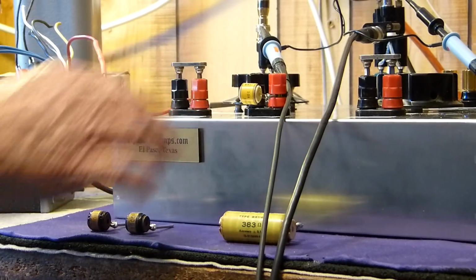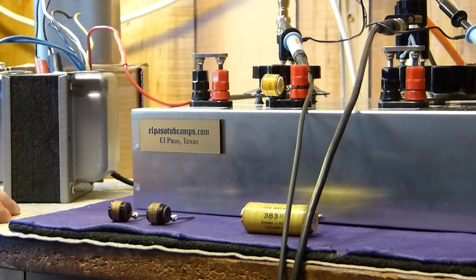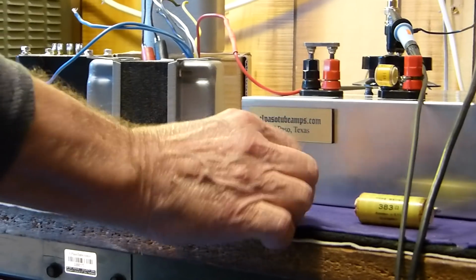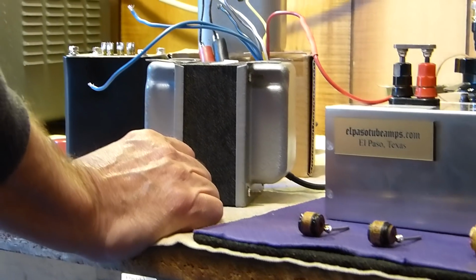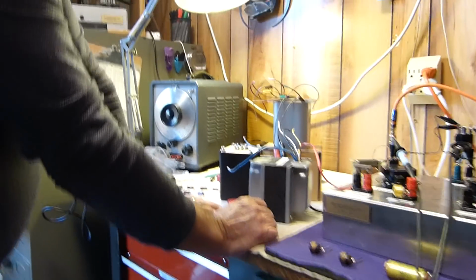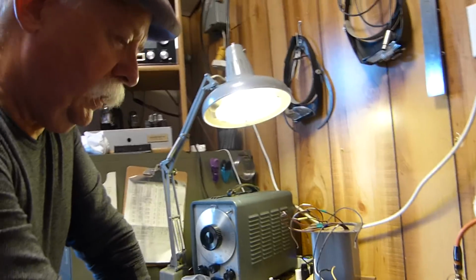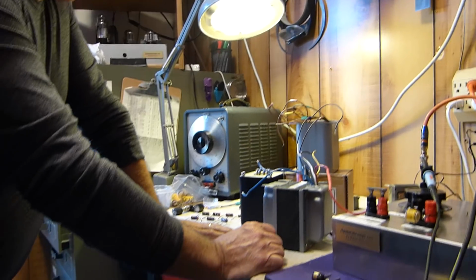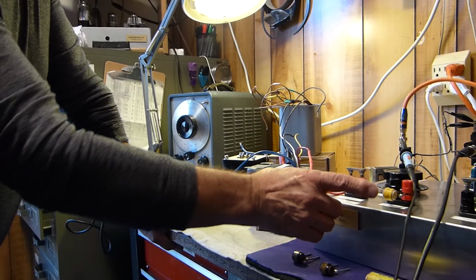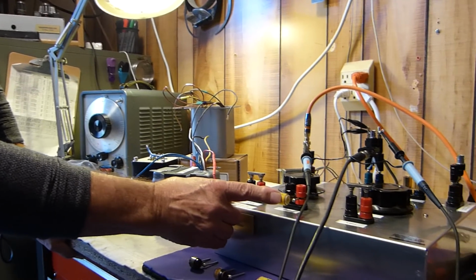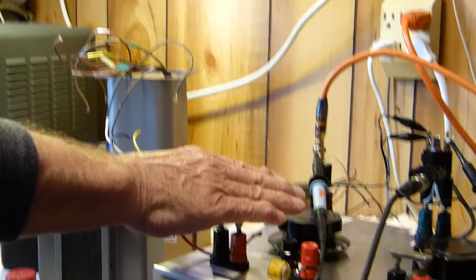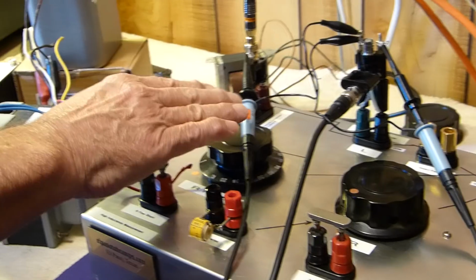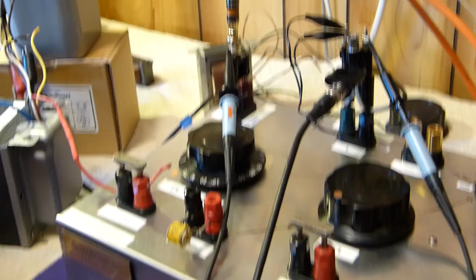These 4 resistors right here are from 300 ohms to 10K, and these are 1K and 2K for something in the middle. You want your phase shift to be enough that you can read it reliably, and yet low enough so that you don't start picking up too much noise. Like if you put a 50K in here or 100K, it starts getting really noisy. By the way, I'm using 1X probes, not 10X. I don't have to use the 10X. The 10X just makes the noise go up.